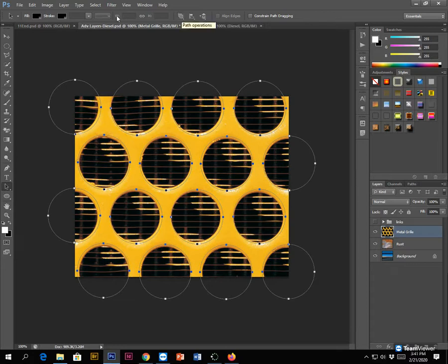Up at the top, in your option bar, there's a menu, Path Operations. There's like these 3 buttons. You want the first button of these 3 buttons, Path Operations. Click on that and choose Subtract Front Shape. Okay? If it's set to Combine, the next step's not going to work. So you need to set it to Subtract. That sets the function of this path.